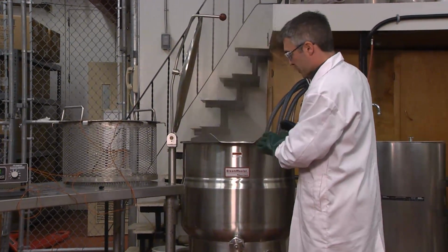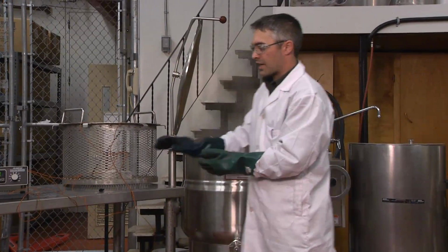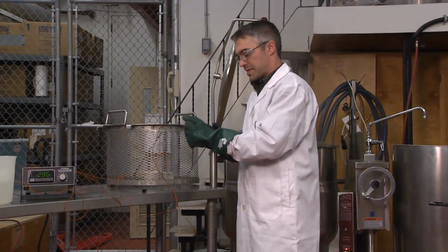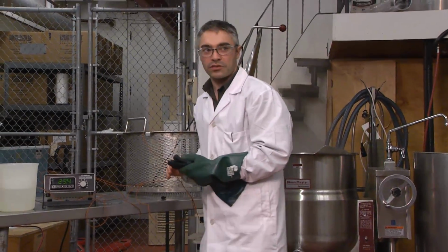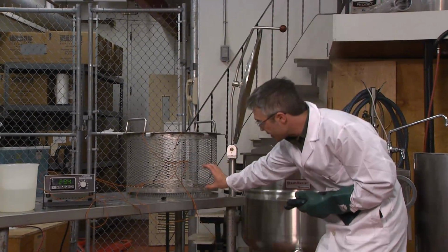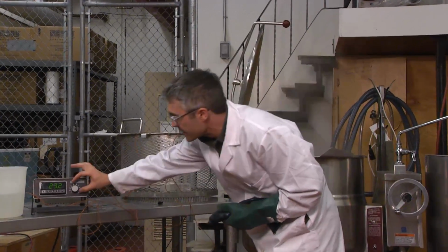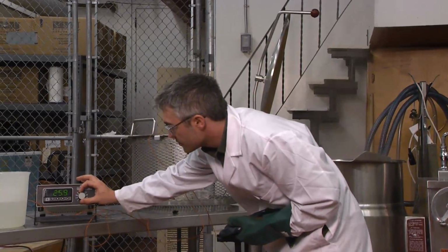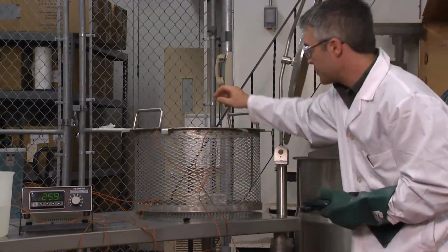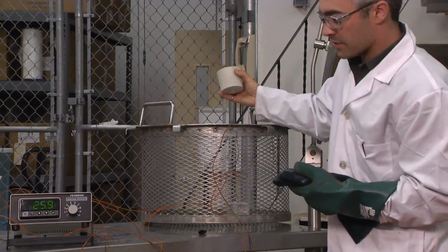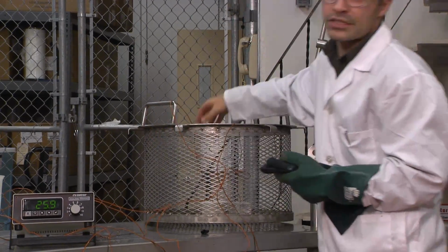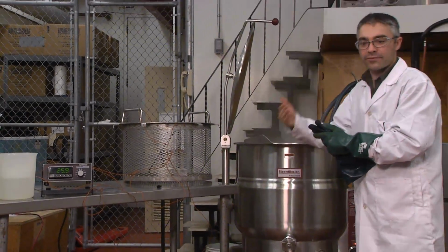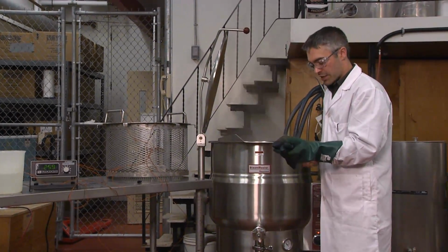Okay. Once your water is completely boiling, you've calibrated your instruments and you've determined the ambient temperature of the air, which will serve as your delta T. We'll be putting in these objects at approximately, if we look at one of the objects, this object corresponding to this channel is currently at 25.9 degrees Celsius. We'll be plunging this into 100 degrees Celsius and waiting for the very center of that object to come up to 100 degrees.